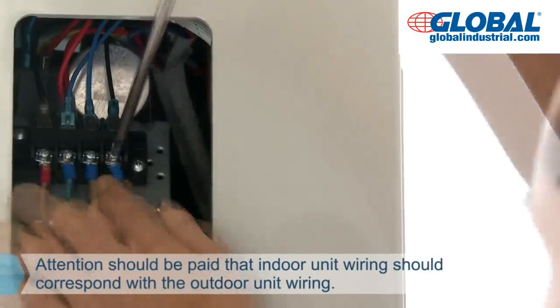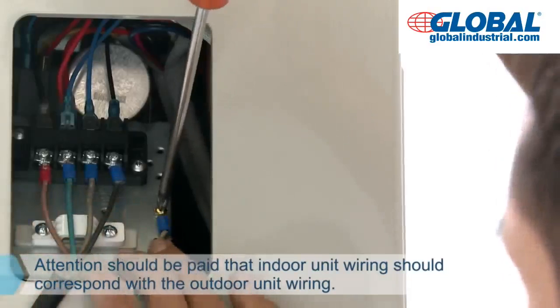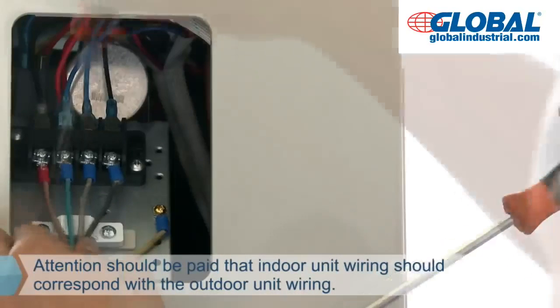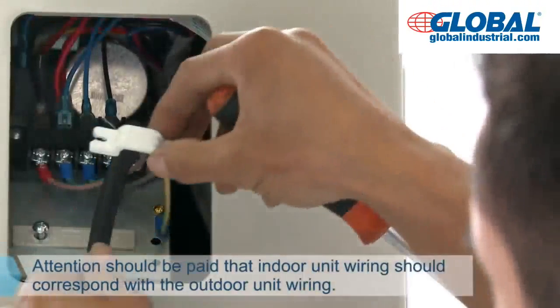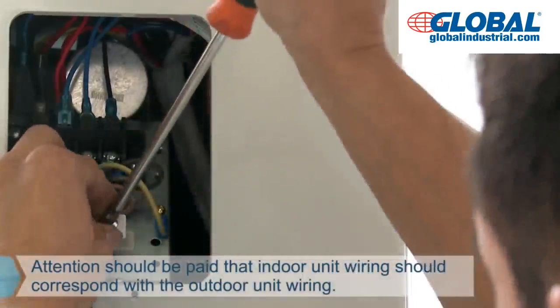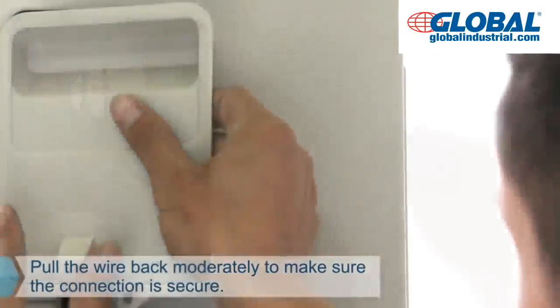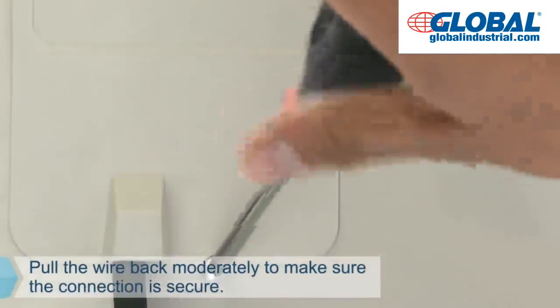Unscrew retaining screw of press wire card. Remove the press wire card. When threading the wire, pay attention to maintain suitable curvature, and the wire shall not be pulled too straight. Mount the press wire card and tighten screws. Pull the wire back moderately to make sure the connection is secure. Mount the large handle.